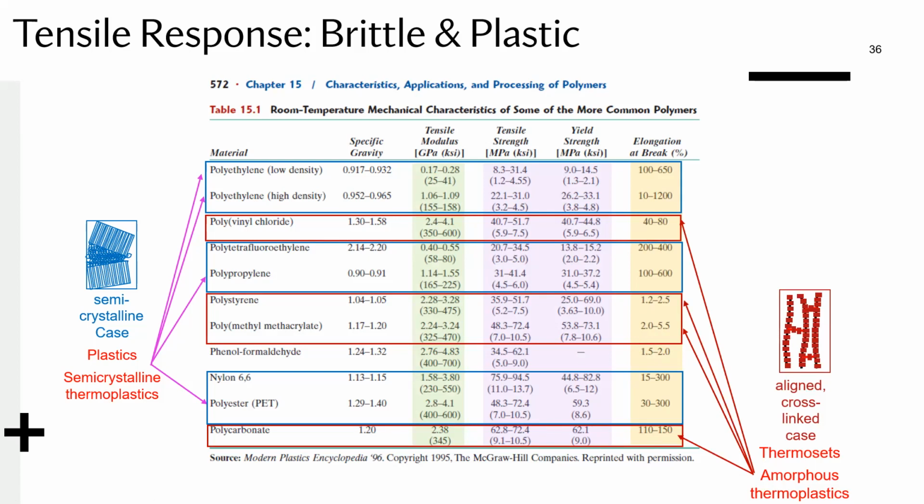Now, if you look at their elongation, they're going to be really small. Maybe the maximum here is 40%, 80%. That's actually quite exceptional. They usually just have a few percent. You've also got a really high percentage, I would say, with these brittle materials at 110%. That's quite a lot. But again, you can see the distinction between these two: these are hundreds of percent, so they can go up to 1,000. These max out around 100, and even that is quite a lot.